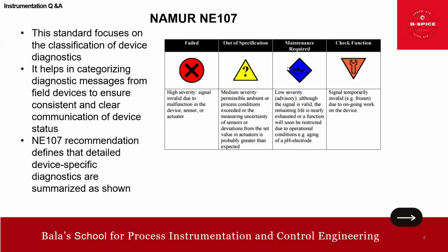Okay. Then maintenance required, low severity. Although this signal is valid, the remaining life is nearly exhausted or a function will soon be restricted due to operational condition, probably aging, or in this case, a pH electrode aging. Okay, this is maintenance required.